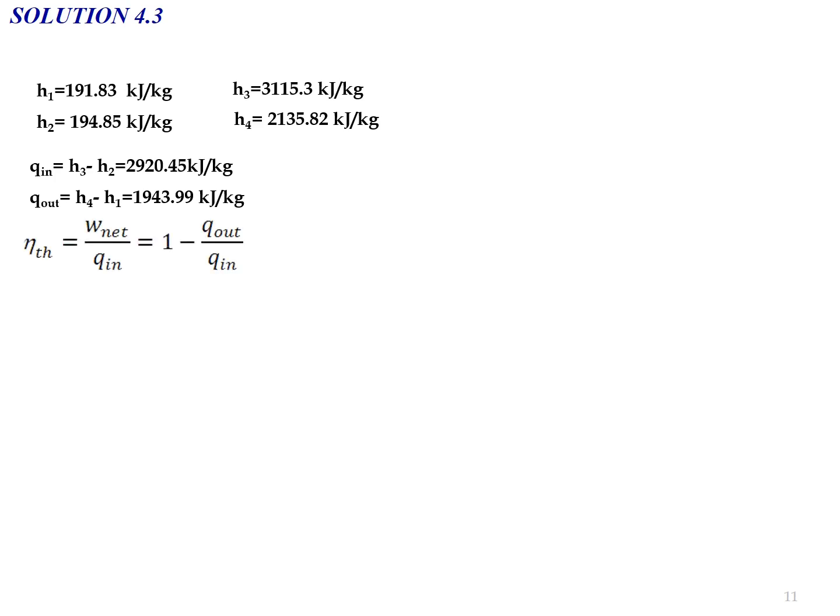So we know that the thermal efficiency formula equal to 1 minus Q out divided by Q in. So substitute the values of Q out and also Q in. So we will obtain the thermal efficiency value for question A, where the thermal efficiency for the Rankine cycle for the first case will be 0.334 or 33.4%.